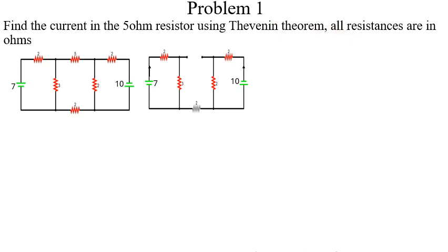So first of all, what do we do? We first have to calculate VTH. So I write my VTH here, and the direction is this way. We realize that we have to apply KVL in every loop in order to be able to find it, because there is a loop here. This is a loop. This is a loop. So I'll also give my directions. I'll take this one in a clockwise direction, and I'll take this one in an anti-clockwise direction.